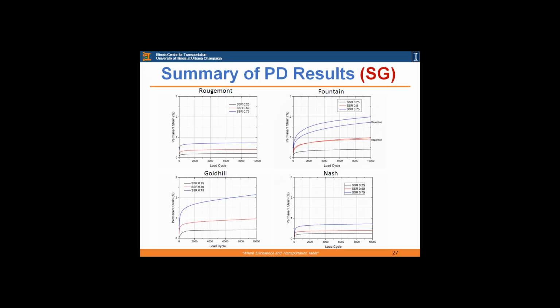Stress ratio is something we apply. Yes, but it's the stress to strength ratio. So as you increase your deviator stress, if you increase your stress states, the amount of stress you're applying, you're stressing the material to higher limits than what it can actually tolerate at lower strength levels.